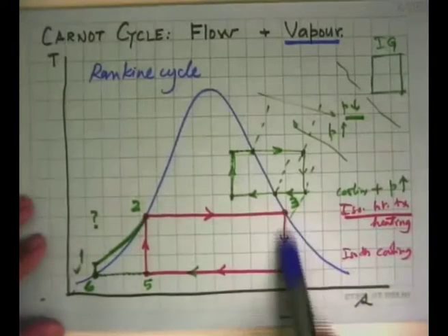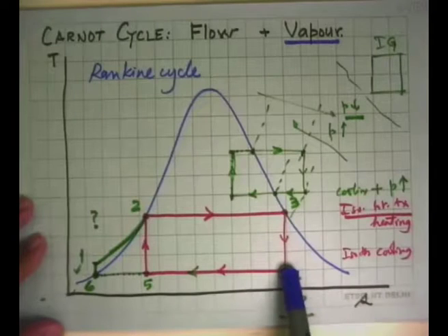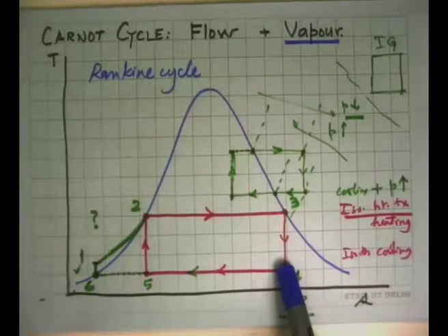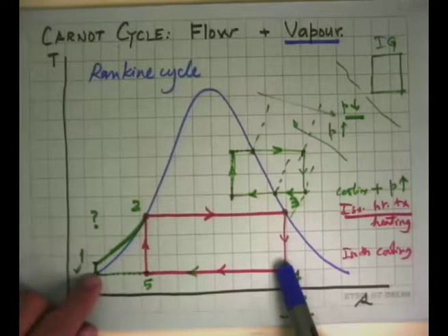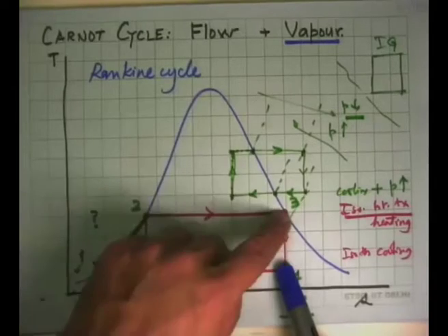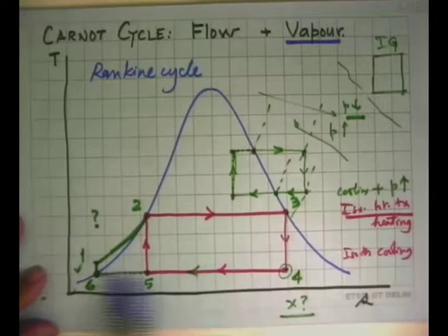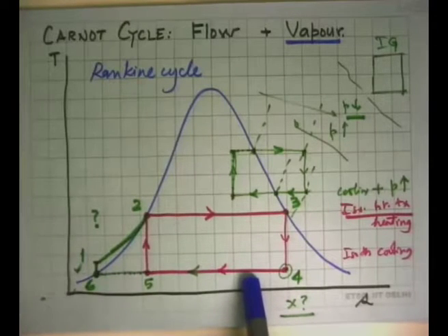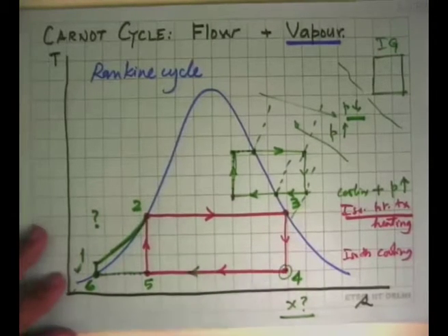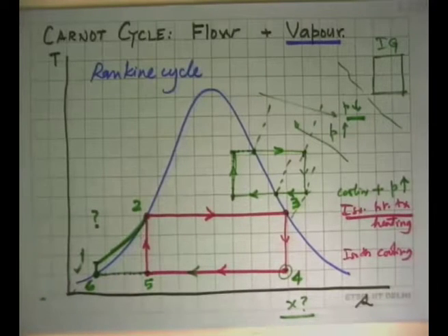So that expansion wasn't exactly like this, but very close to this. And then after expansion, that was an open system, that steam was thrown into the atmosphere. And then we keep getting fresh water, put it in there and do this process, expand it, throw it out. So 4, 5, 6, the heat rejection process was not there in the original steam engine or any steam engine that came afterwards, but this formed the basis of trying to make the flow type of a power cycle, which is the standard thing now in all types of power generating systems.